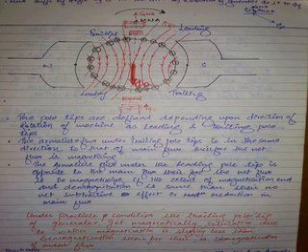In this region, if you say flux density increased, in this region decreased, if the increase is equal to the decrease, what is the demagnetization? There is no demagnetization. Is the point clear or not? If the increase under the trailing pole tips is equal to the decrease under the leading pole tip, then what is the net demagnetization, the total demagnetization? Zero. Yes or no?